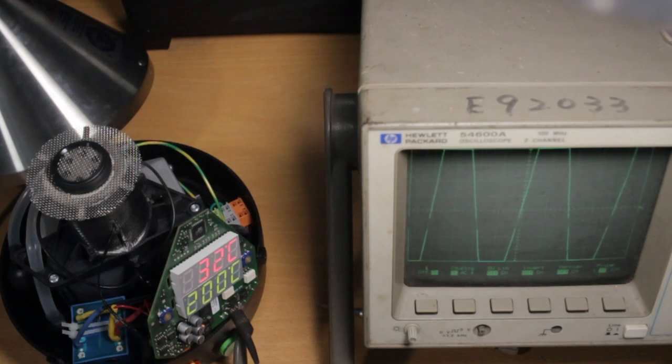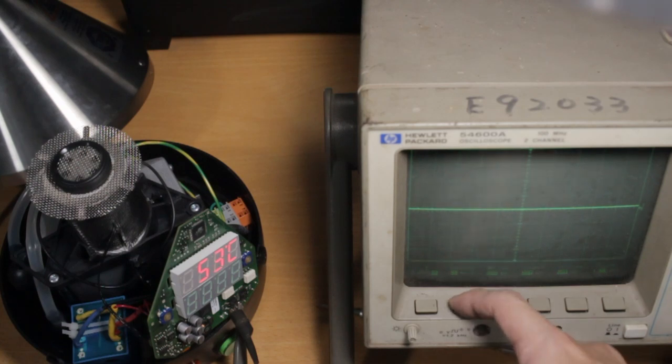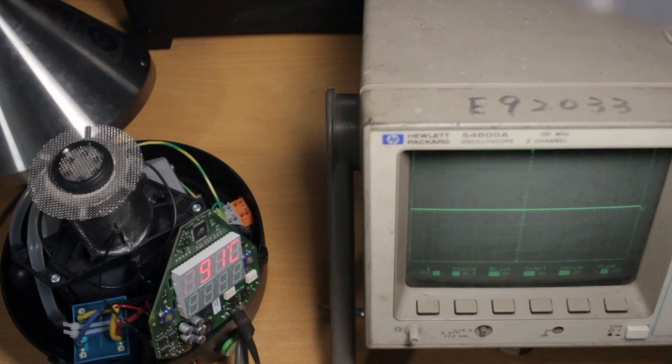Okay, now what you see is the heating element waveform. They pass full waves through the triac to the heating element. I think this is reasonable. If you make your own heating element, the code is much simpler this way. You just collect temperature data and use PID computing to decide how many waves you need to pass through to reach the desired temperature.